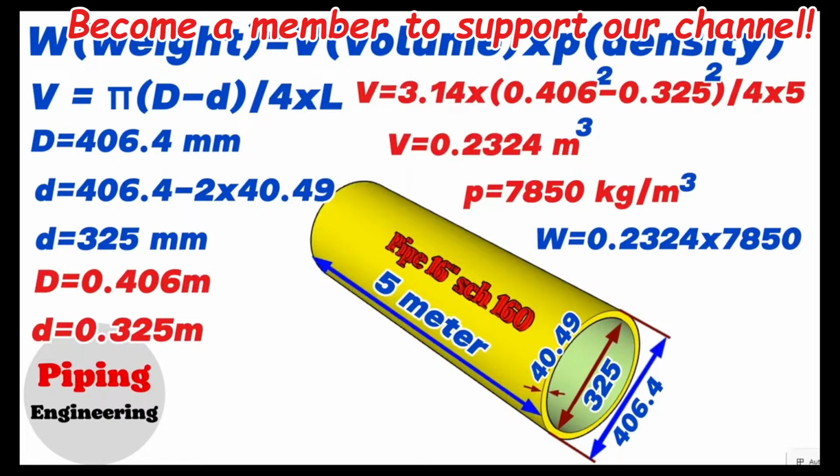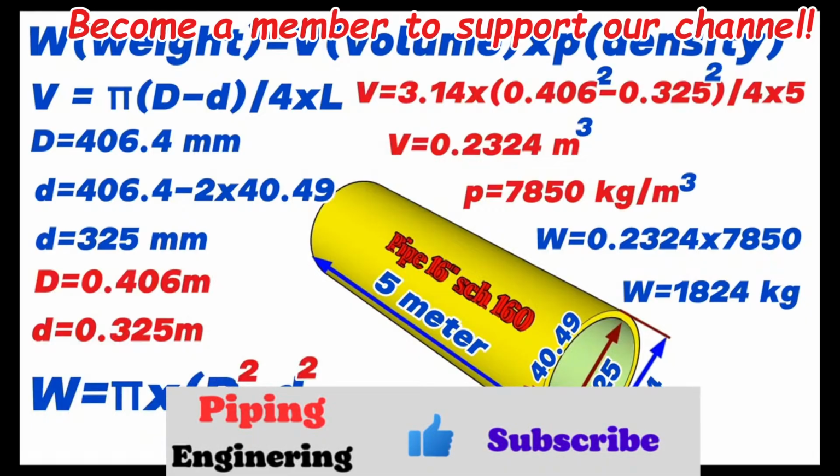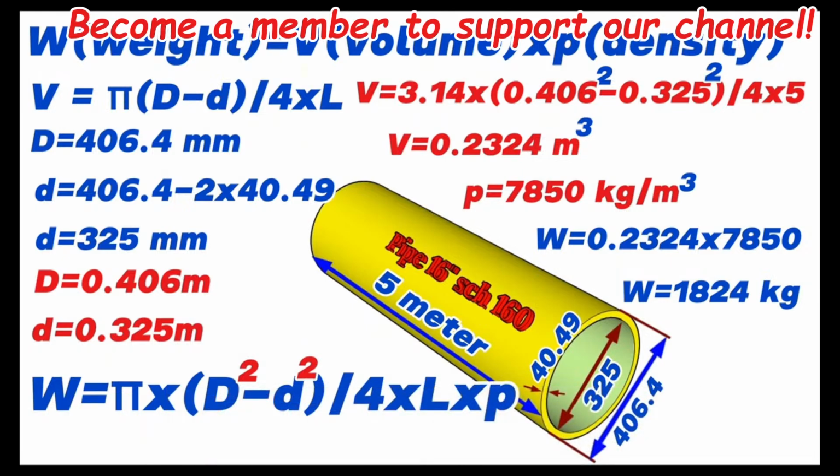So, we calculated and found that the weight of the 16-inch Schedule 160 pipe in our example will be equal to 1824 kilograms. Summarizing what we learned in this video, we can also use this formula to find the weight of the pipe. Weight is equal to pi multiplied by, in brackets, the squared outside diameter minus the squared inside diameter, divided by 4, multiplied by the length of the pipe and multiplied by the density of the pipe material. By using this method, you can easily calculate the weight of pipe pieces in any pipe drawings.